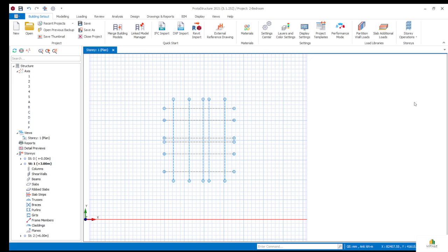So let's go to edit story, then click on edit story, right? Then you see a dialog box which has the title edit story, and you see a box, because we are dealing with a 2-story building. You see 2 rows in the box. Let's say you see 3, but the top one is for the titles, and for the rest you see 2 rows which have info and story. You see story 1, story 2. That means we are dealing with a 2-story building, right? Then you see the height in millimeters, 3000, 3000.